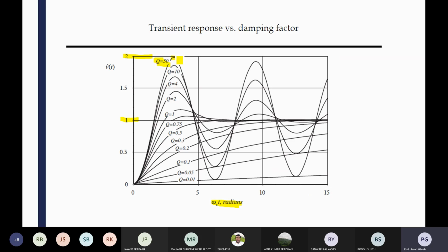Okay, those oscillations. When you are changing your reference value, that reference voltage tracking you are doing, you are observing to check your disturbances. Suddenly you can see that a peak is coming, twice that reference value, and then it is settled down. That means a huge value appears across your switches. Not only switches, maybe inductor and capacitor, all those connected in parallel with this. So it directly has an effect on your devices and components, and that may damage your system. You should keep that in your mind.